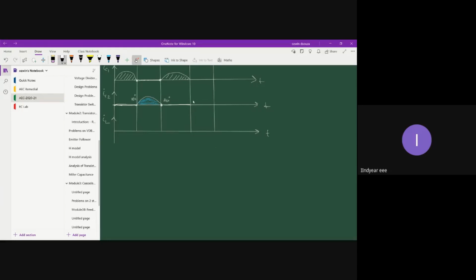And once again, the transistor comes into conduction for the next half cycle. So basically what is happening is, the two transistors are working in alternate half cycles. When IC1 is present, IC2 is off. And when IC2 is present, IC1 is off. By doing so, there will be a complete 360-degree cycle, a full cycle, available at the load. So this is the wave nature of class B power amplifier.